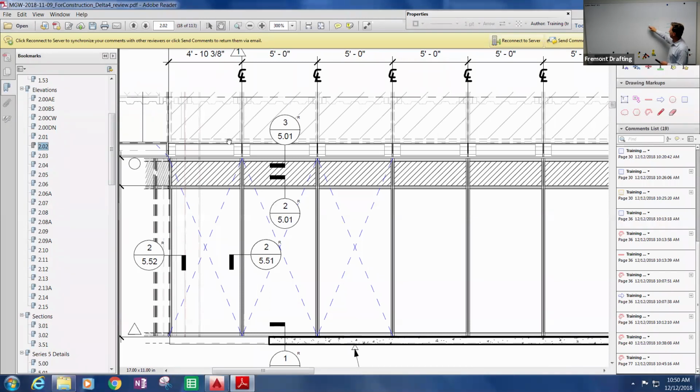I'm grossly exaggerating. It might lift that much, but if you consider that this point is usually 5 feet away, it would never tip to that degree. So our verticals in the male-female connection, everything slides. There's not much difference in how that looks as far as the width of the mullion. The 2 3/4 might separate a little, it might get a little closer as it's moving, but in general, it's staying relatively 2 3/4 as it's moving that way.